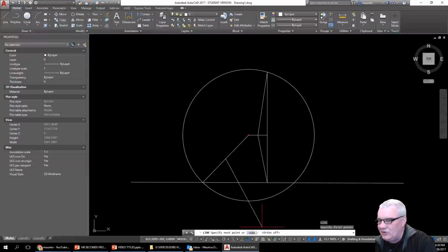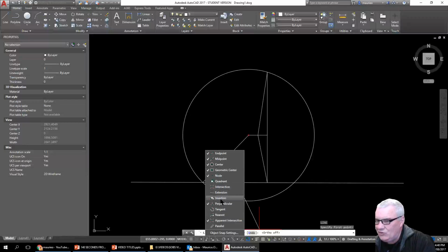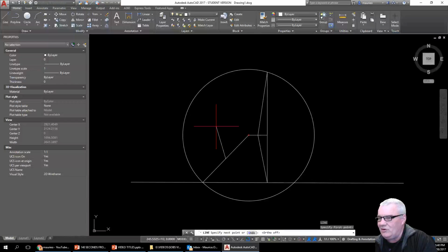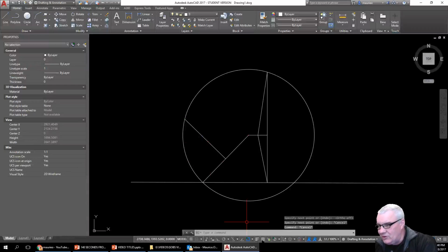Now there is this option here that we can click in here and turn off nearest, which we sometimes can use, and that'll give us all of the points on the circle. So that's any point on the circle, like so. We might just want to make any point on the circle like that there. So these are our object snap settings.